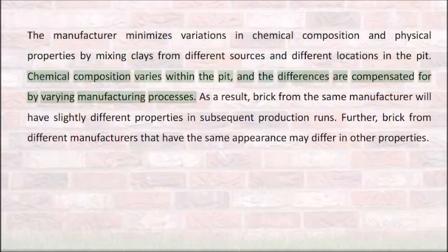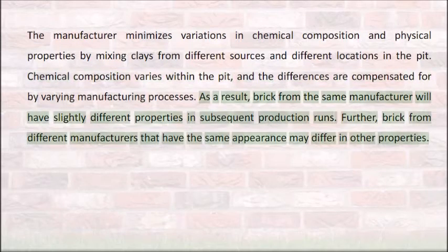Chemical composition varies within the pit, and the differences are compensated for by varying manufacturing processes. As a result, brick from the same manufacturer will have slightly different properties in subsequent production runs. Further, brick from different manufacturers that have the same appearance may differ in other properties.